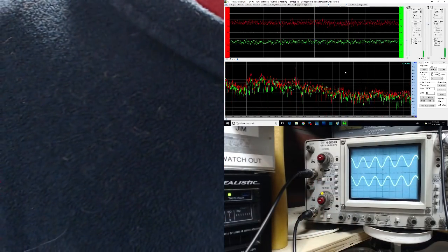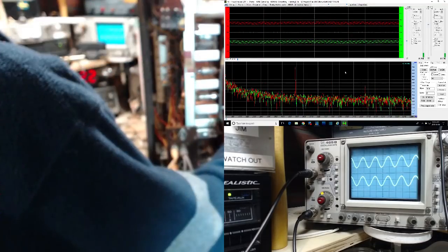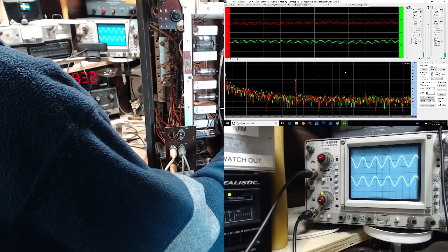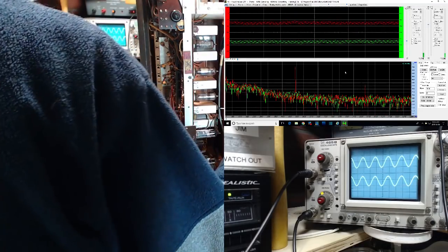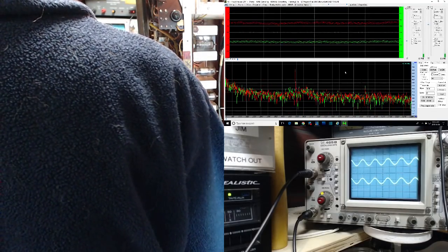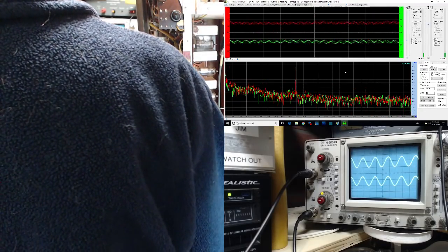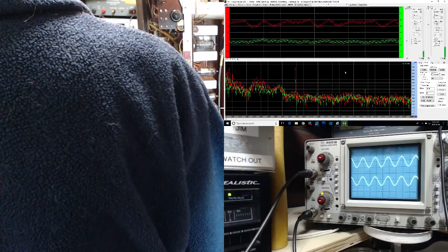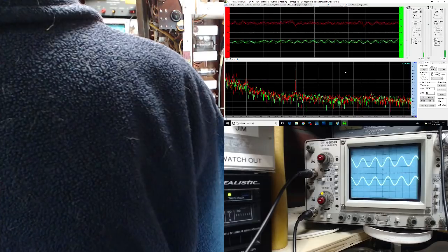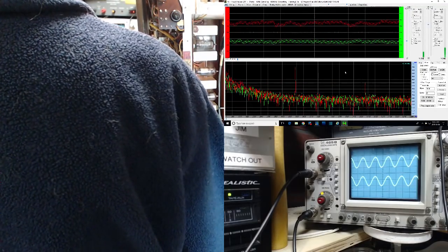Now, this will be shape and harmonics. Okay, so I don't really hear harmonics. Let's look at the spectrum display now. I see the 5 kilohertz standing there quite proudly, and right around 10 is a harmonic. There, now you can see the harmonic.